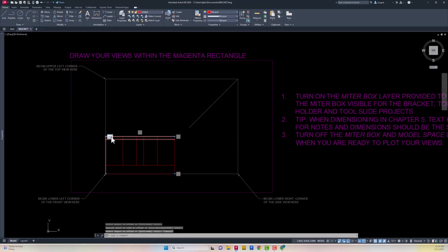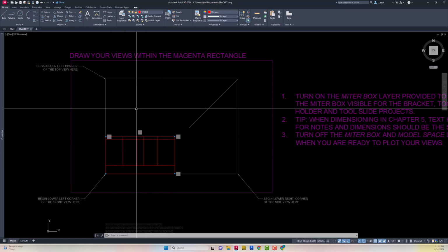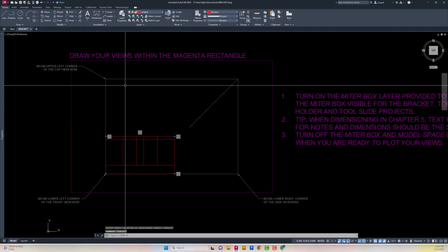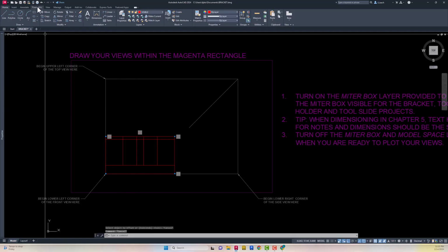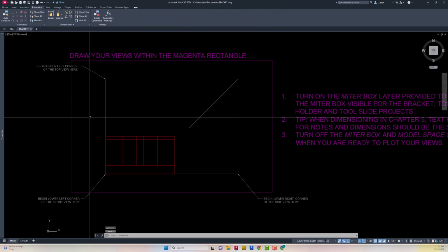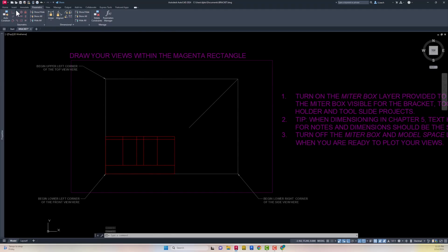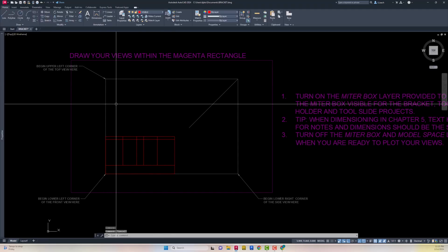You'll notice these constraint boxes pop up. Those annoy me, I'm not going to lie. If you want to turn these off, we go up to parametric here, and we can go to hide all. But you're going to notice as we keep drawing, they're going to pop back up again. But I just try to get rid of those. Anyway, what was I doing?